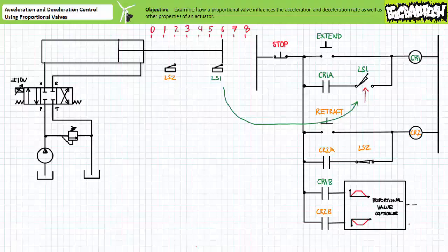Quite obviously, we failed to meet every qualification during the extension phase. 1. The applied load didn't accelerate smoothly, but rather jerked to a start and slammed to a stop. 2. The pressure dropped, then spiked. Finally, 3. The rod failed to fully extend. All in all, an unqualified failure, and we're only halfway through.